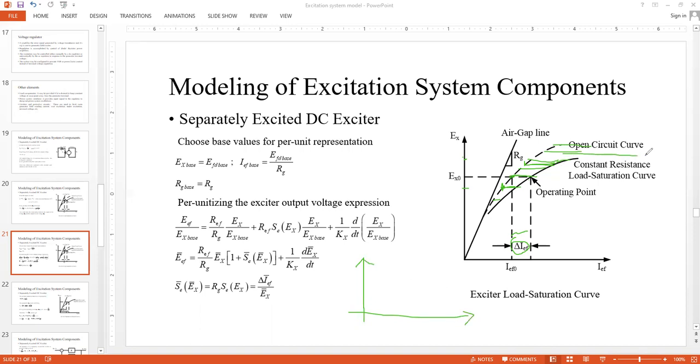How can we change this OCC for a certain machine? Remember, this is open circuit curve that gives you the idea of the open circuit voltage, let's say E0 for a DC generator. What's the relation? The relation is K and phi. Now, I don't know whether you remember this old knowledge, which you probably took with me in your 2-1. So this is your OCC, let's say.